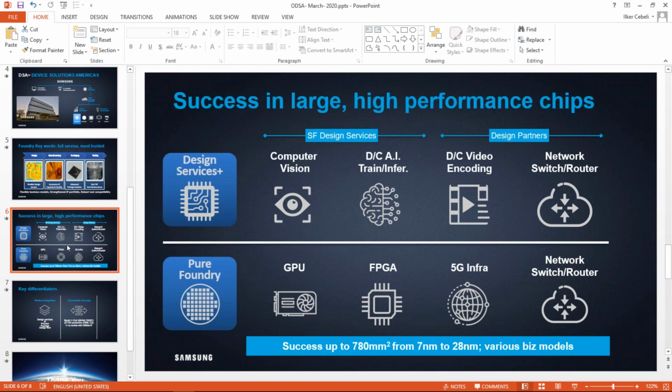However, on the fan out side, at ASE we already have internally in qualification an HBM SoC integration with two HBMs using fan out, where we're using 2 micron line and space RDL layers, and that eliminates the silicon interposer. There has been some optimization in the way we do our designs, but with the way we do the vias combined with the 2 micron line and space, we are able to route HBM using fan out. And who is speaking, if I may ask? This is Elko from ASE.